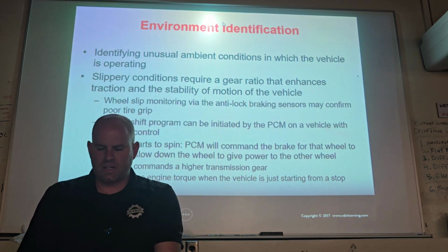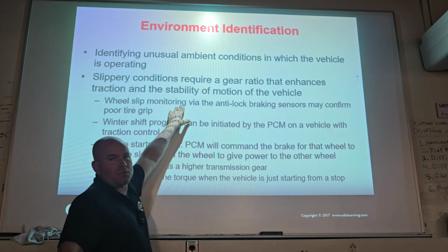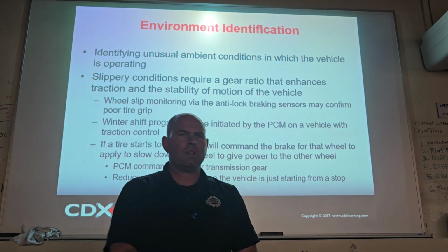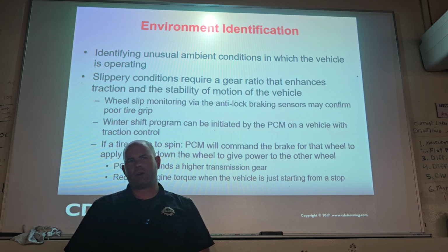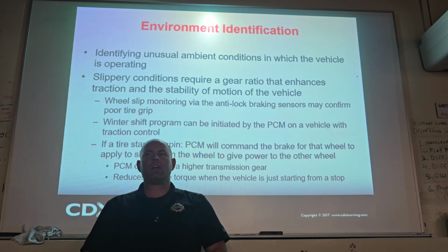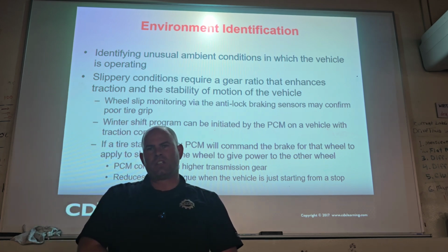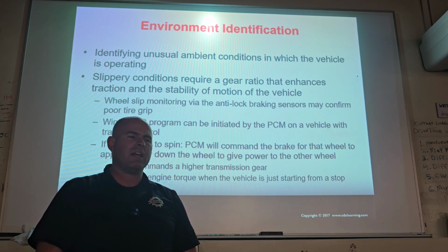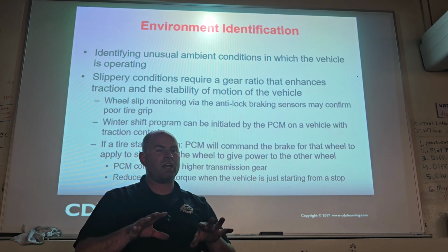What about if you're wheel slipping? If you're wheel slipping, the transmission can function differently. So let's say that you hit a bunch of snow. What do you think you want the engine to have, more power or less power? Generally less, because you're going to spin more, right? So they can cut power at the engine, but it can also make your shifts earlier and softer too. So there are some that would look at your vehicle speed, your wheel speed sensors, and if you're slipping a lot, it might say, whoa, we're going to go in snow and ice mode and soften the shifts a lot.